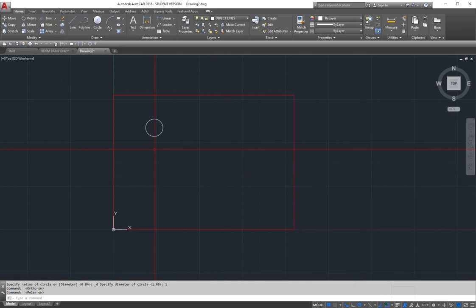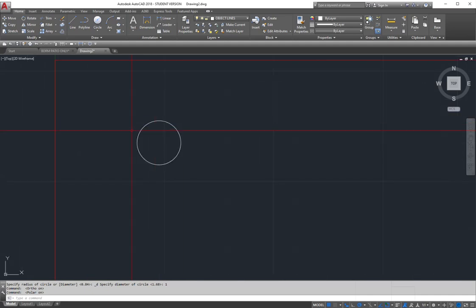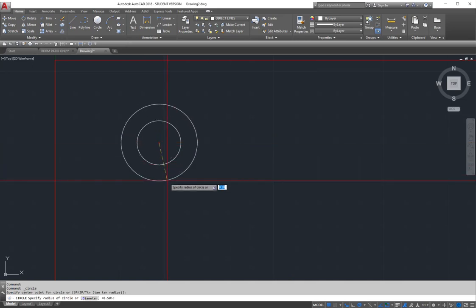And so I'm gonna say, well, I need now the second circle on the outer part of this shape, which is going to be with a radius. Now the one that I just drew was a diameter. Now the second one is with a radius 2 times, so that's a radius of 0.875. So I go again and select my center radius, go to the center point right here, and my radius is going to be 0.875, and I hit enter. Now I have that part.